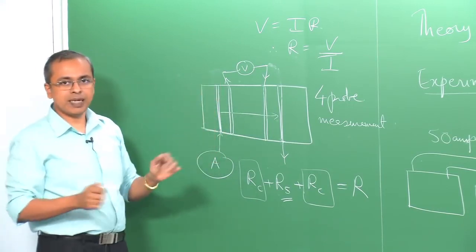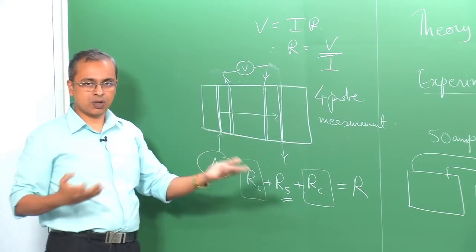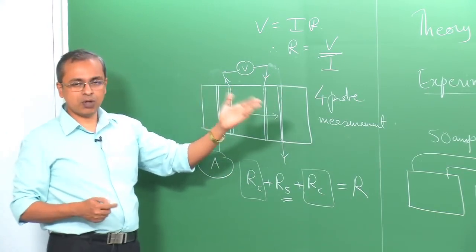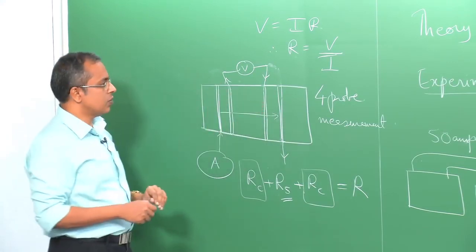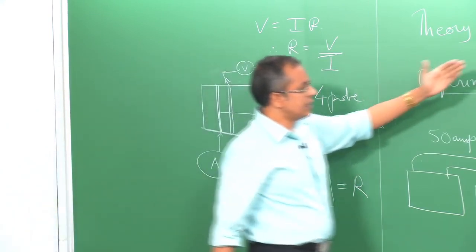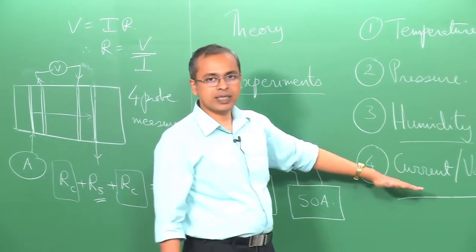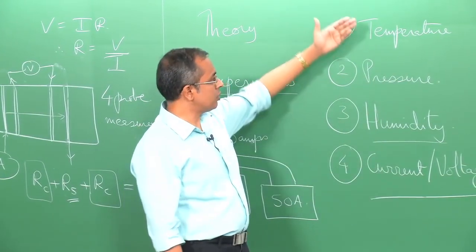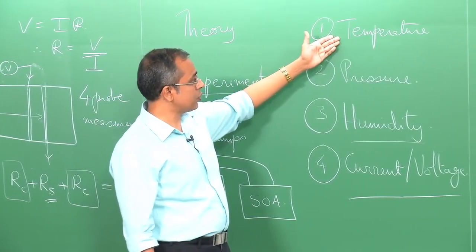Always there are numbers on display and always you can note down those numbers, draw ratios, write up ratios, draw graphs and so on. I am just pointing out that in straightforward experiments that we commonly do, there are so many sources of error, right. So, to sum up, we have seen temperature, not a whole lot on pressure, but humidity and current and voltage, and I have just shown you that these are all common quantities that you measure. I just pointed out that there is so much room for error based on where you may put your sensor.